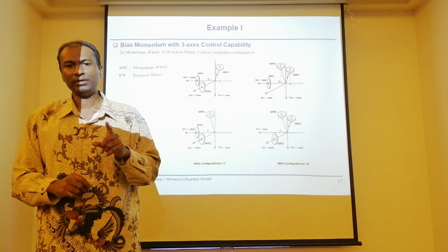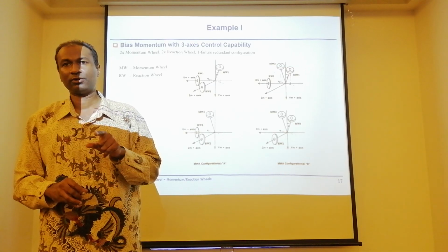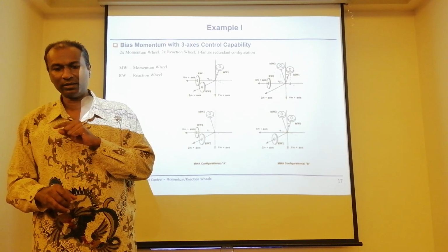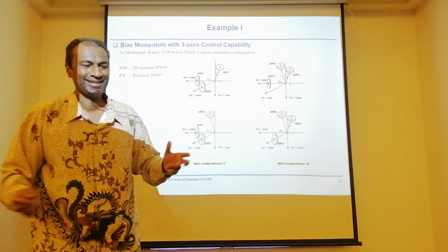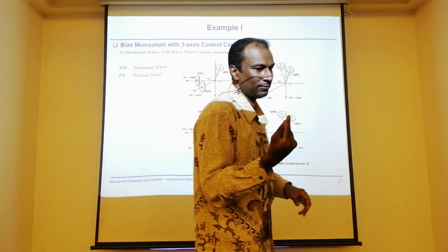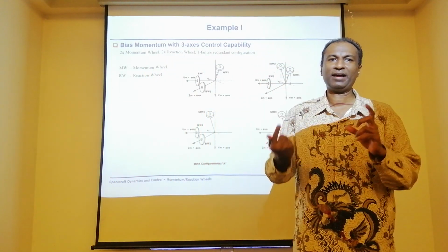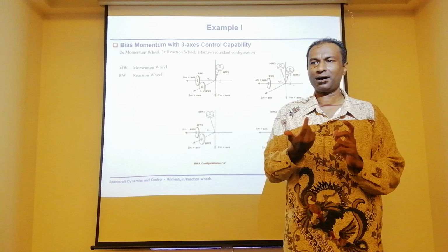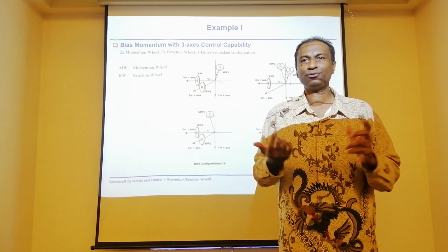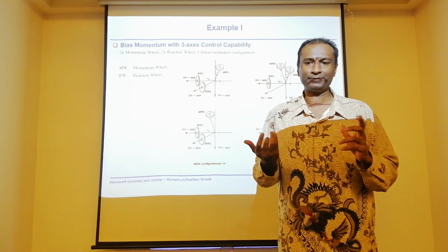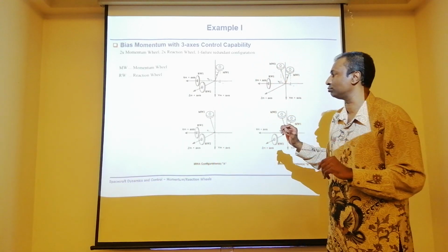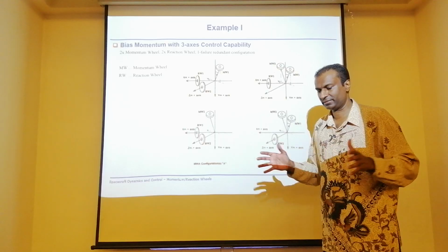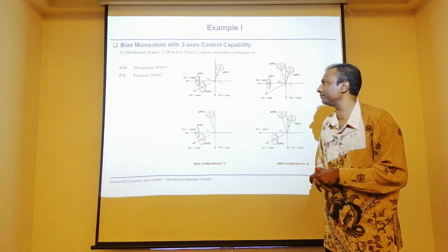A redundant wheel is mandatory because when there is a wheel failure in a very long mission, 10 years, at least 1 wheel is there, basically like a spare tire in the car. Of course now you can do run flat. But we have that in order to have a safety margin of operation.